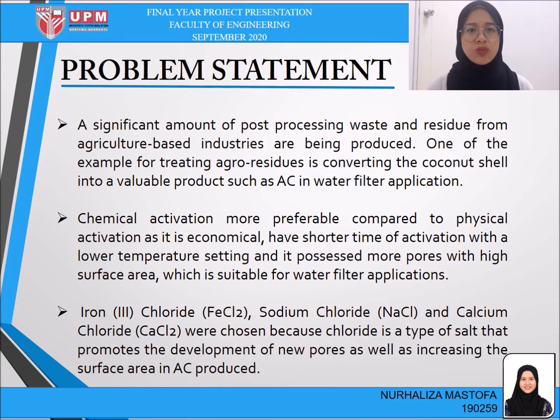A significant amount of post-processing waste and residue from agriculture-based industry is being produced. One example of treating agro-residue is converting the coconut shell into a valuable product such as activated carbon in water filter. Chemical activation is more preferable compared to physical activation as it is economical, has a shorter activation time with a lower temperature setting, and it possesses more pores with high surface area. Thirdly, iron trichloride, sodium chloride, and calcium chloride were chosen because chloride is a type of salt that promotes the development of new pores as well as increasing the surface area in the activated carbon produced.